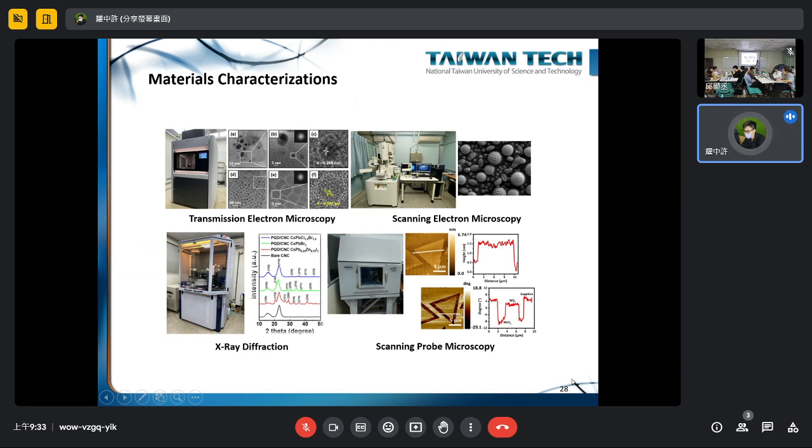The diffraction peak here, what's the use of that? From this, you can calculate back, because you know the wavelength of your X-ray, right? And then you know the angle. From this, you can calculate back to the crystal structure.